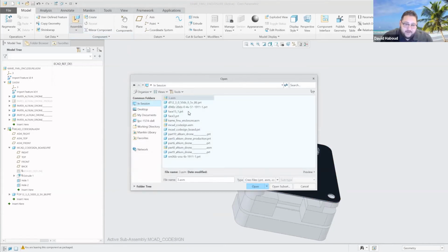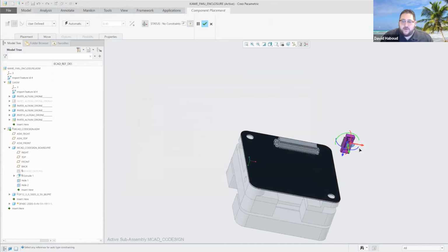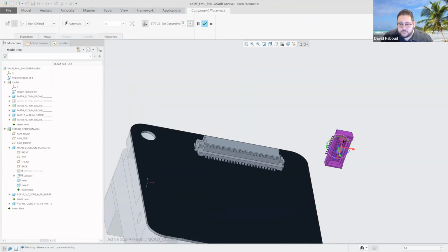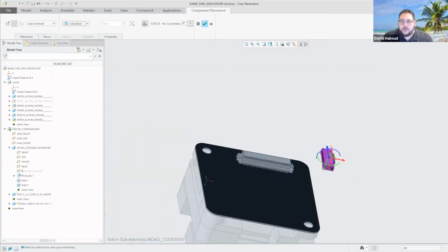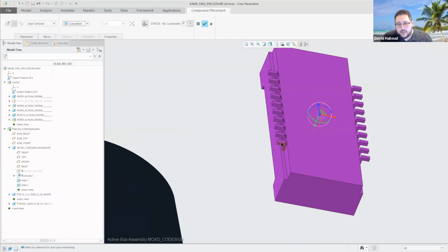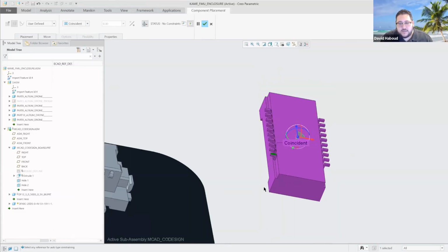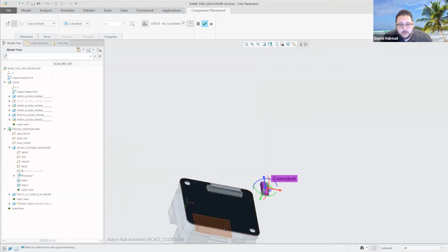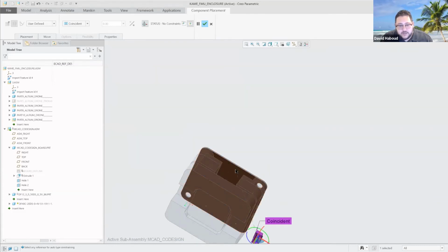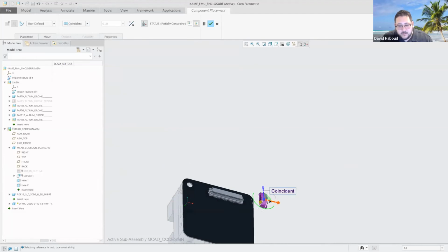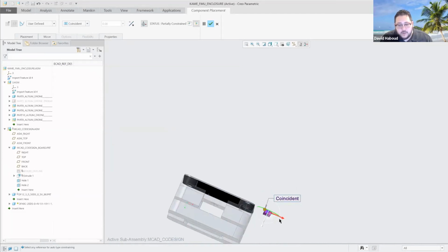and I'm going to add some more components. I have DF40 now. And when you are constraining, I think I mentioned this, but just in case, it's nice, you do the flat side right there. And this one's actually going to be on the opposite side of the board over here. And we're going to do something very similar.